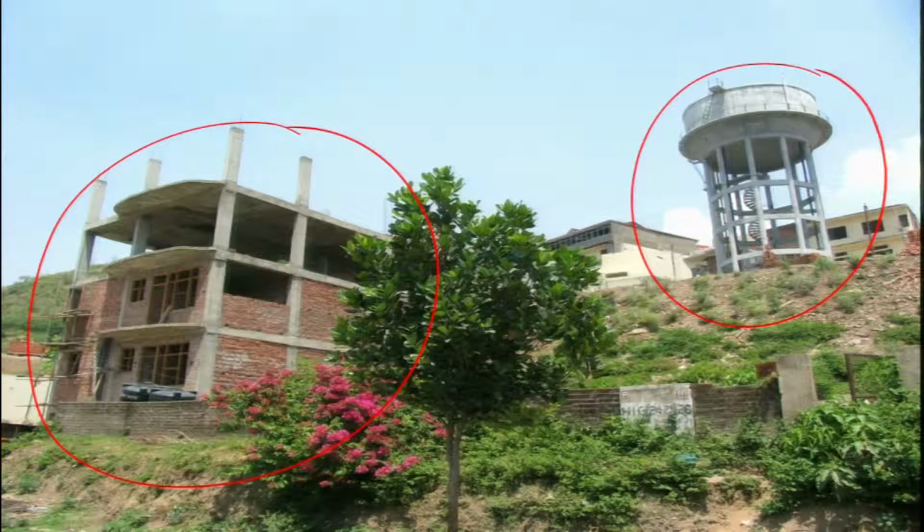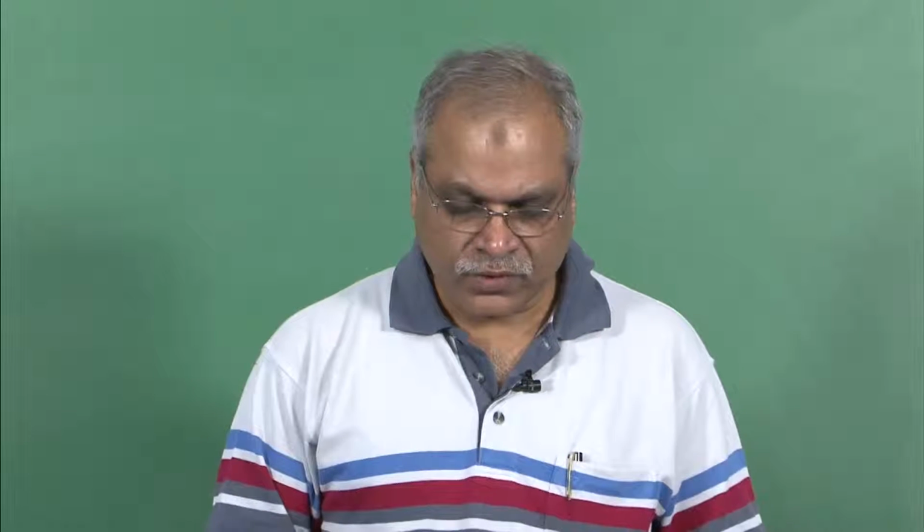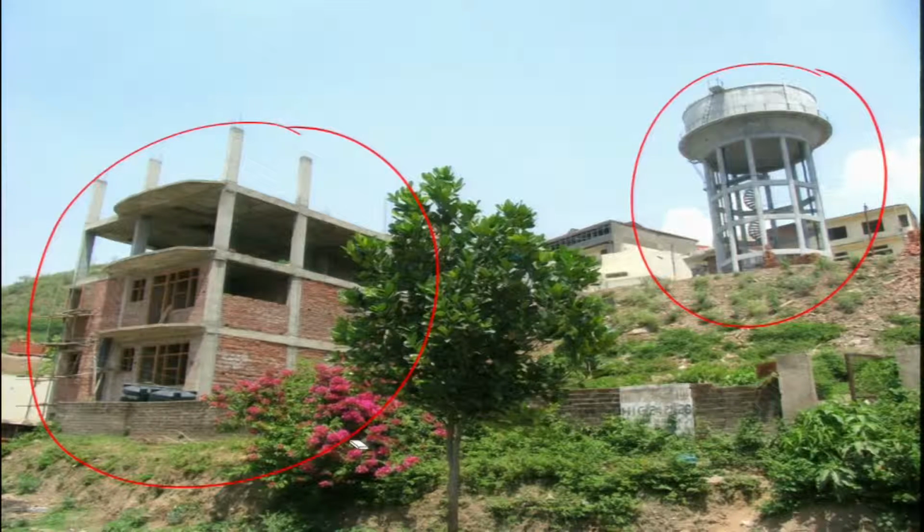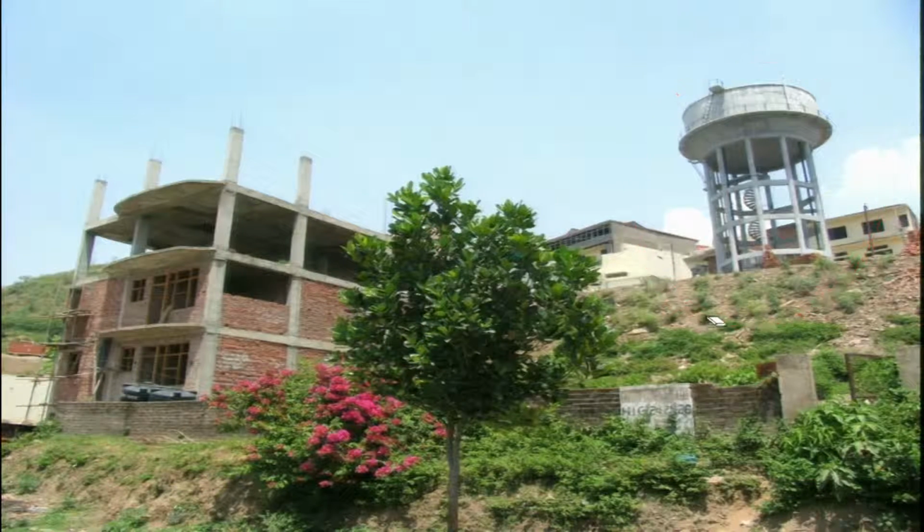So both movements will be experienced here, and you can think over what will be the ground acceleration in this area. Okay. So this area for sure will observe total damage. So this is one example which I wanted to show you, of the importance of delineating or identifying the fault lines from satellite photo interpretation.